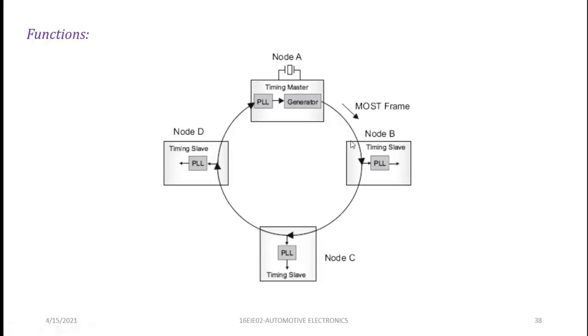Based on the signal it is going to synchronize itself, and it is going to parse the frames, and it is going to process the desired information, that is whether it is going to control or whether it is going to receive the data or going to send the data, and it is going to add the information based on the free slots that are present in the frames, and it is also going to transmit the frame to the successor, that is the next node. Am I right?